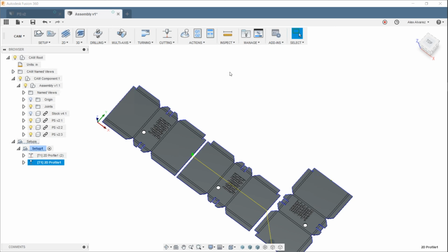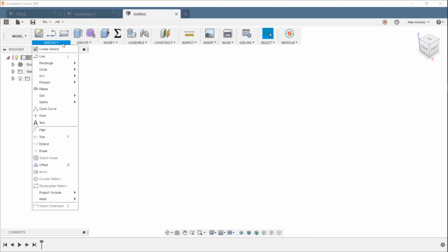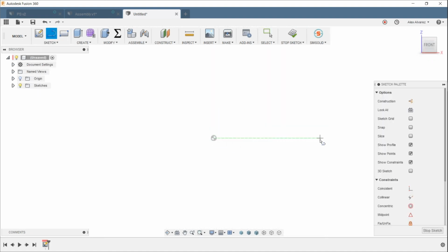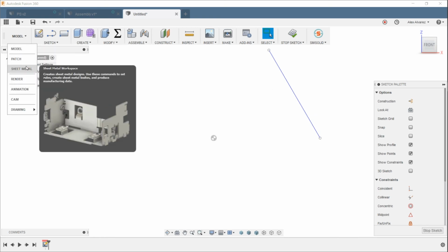Let's see what else. We have another question here. Someone wants to see a cone. I guess that's something a lot of people have a question on, actually a sheet metal cone. You can do those. It's a little counterintuitive how that works, but I can show a quick and dirty way of doing it. I believe I showed this also in the last webinar. You just want to create some sort of arbitrary line. You would dimension this based off of a max and min diameter if you have one, and you can definitely do that. But for now, I'm just going to do a quick arbitrary angled line.